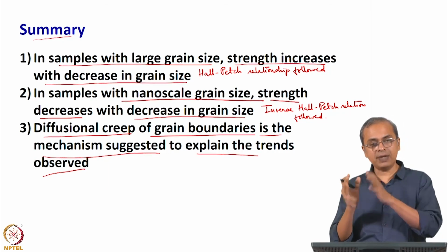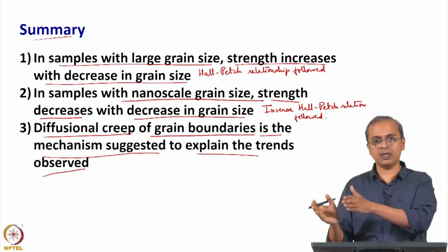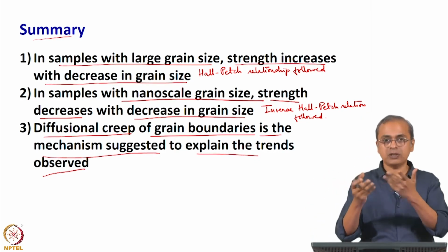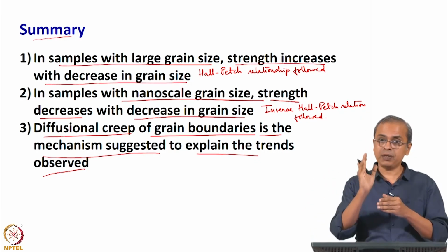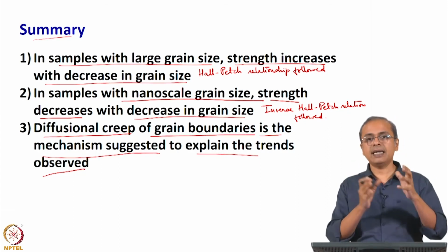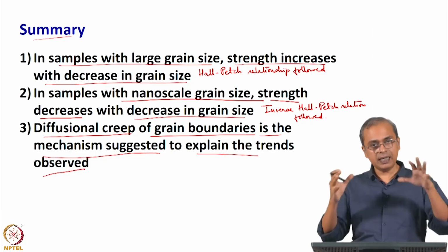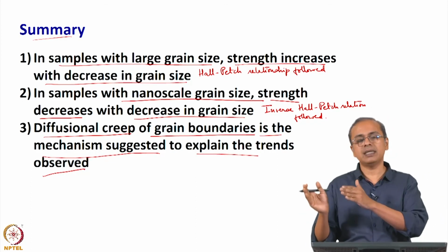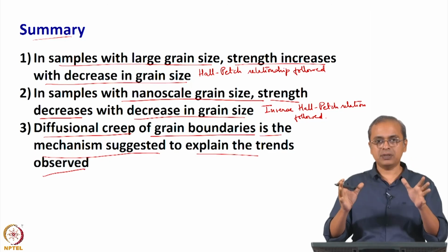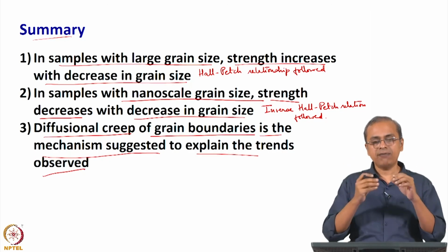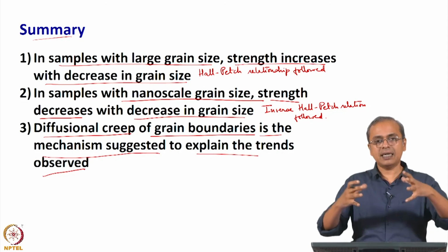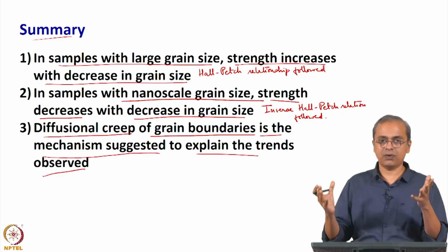So, atoms and vacancies can move through the grain as well as through the grain boundary. Generally there are more defects at the grain boundary, because there are incomplete bonds. Therefore, the movement of atoms along the grain boundary is typically faster than it is through the grain. However, in typical materials the amount of grain boundary that is available is less. Therefore, if you total up the number of atoms that are diffusing through the system, the fraction that diffuses through the grain boundary is less than the fraction that diffuses through the grain, and that is how you see the overall diffusion coefficient of that material.